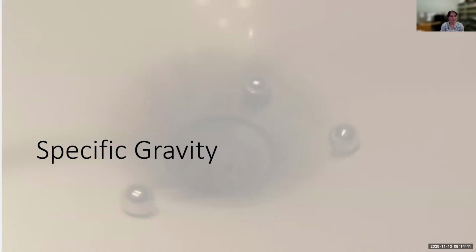so let's move on to specific gravity. We looked at solids concentration and what that tells us about the concentration of our chemical solutions. But what happens if our sodium hydroxide solution is getting old and we need to know the current concentration to make sure that we're dosing properly? Or what if we want to calculate something else? Like what if we need to know the weight of our solution? Well, we can use specific gravity to help with these things.